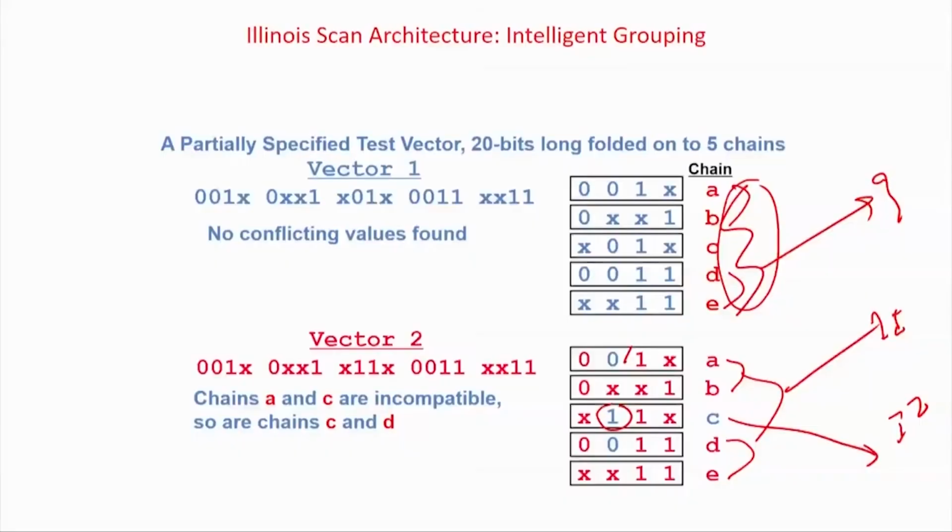So how exactly do you partition? And what is the most optimal way of partitioning, so that the number of pinouts is minimized and no fault remains untestable? We can solve this by the compatibility graph. This is an NP-complete, very tough computational problem, and you cannot find an exact algorithm for it. It will take an exponential amount of time. So there are a lot of heuristics to do it.